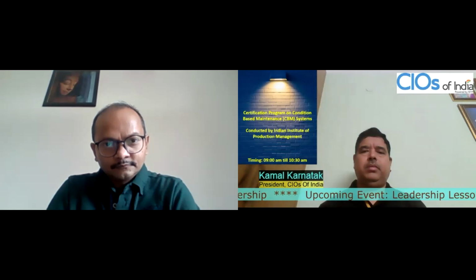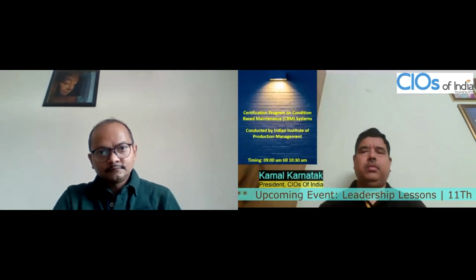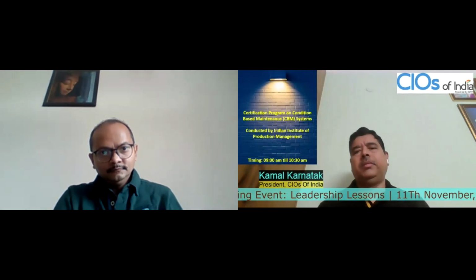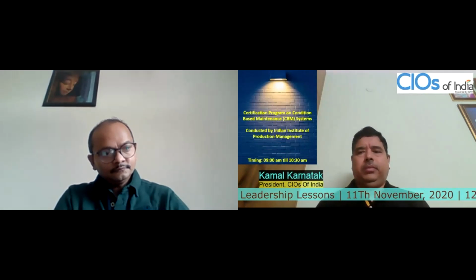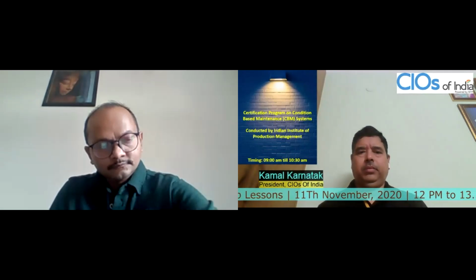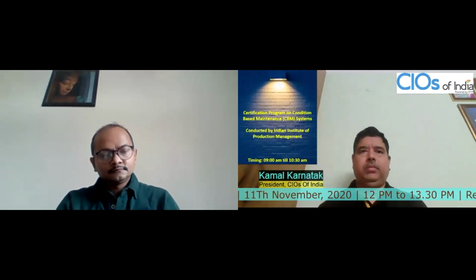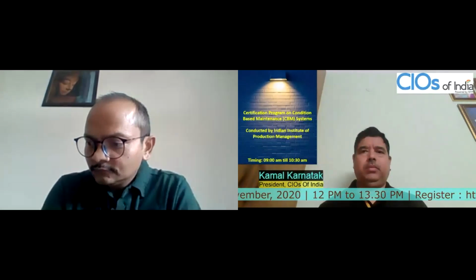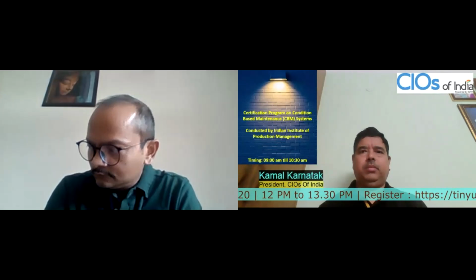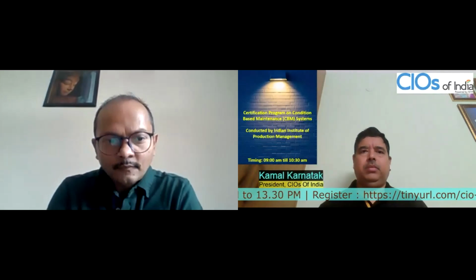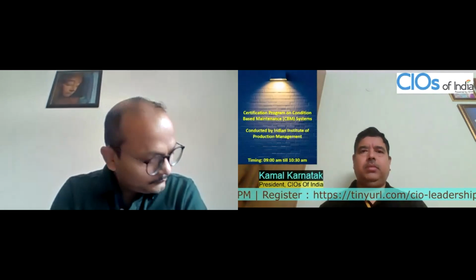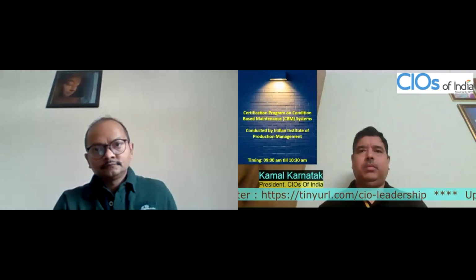While vibration analysis meters have been there for long, now with the use of IoT-based technology, the data can be remotely gathered and all the analysis can be done, including the analysis of the patterns that Vishwajit was explaining. Through those analyses, we can really find out whether equipment is going to fail or not.